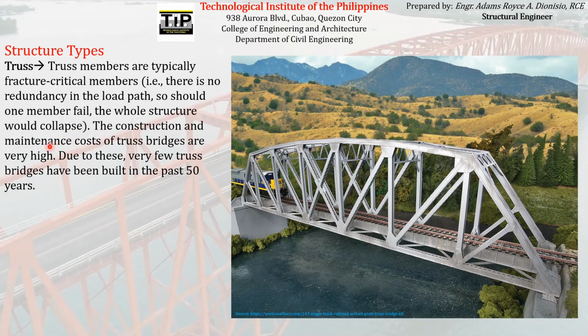The construction and maintenance costs of truss bridges are very high. Due to this, very few truss bridges have been built in the past 50 years. Truss bridges are useful to carry heavy loads, heavy traffic, such as the railways of trains, such as this railway that you are seeing here in the picture. Although the disadvantage of using a truss type of bridge structure is that its members are fracture critical. When we say fracture critical, it just means that if one member fails, the whole structure might collapse.